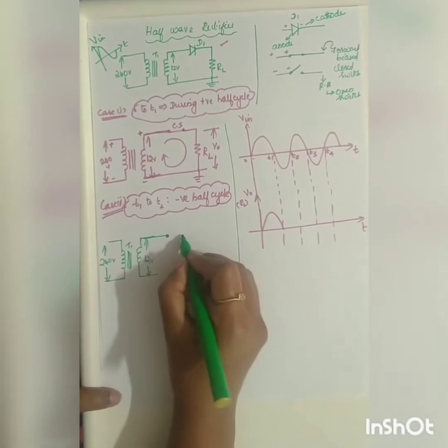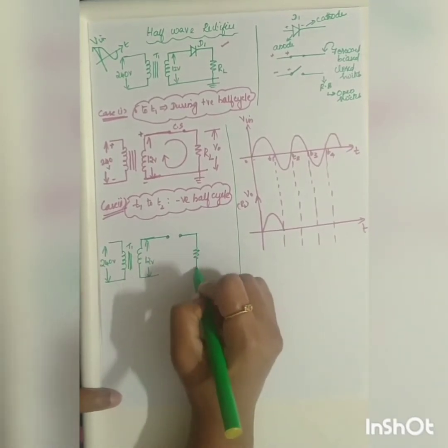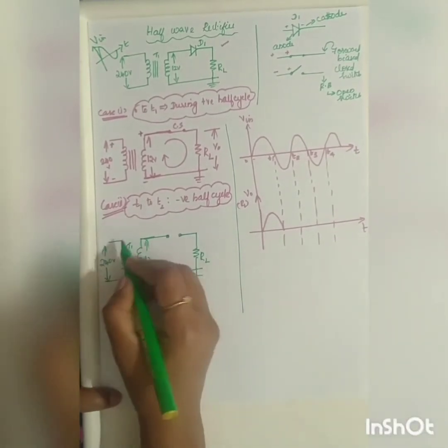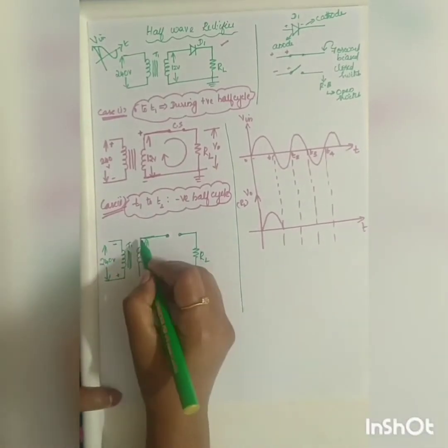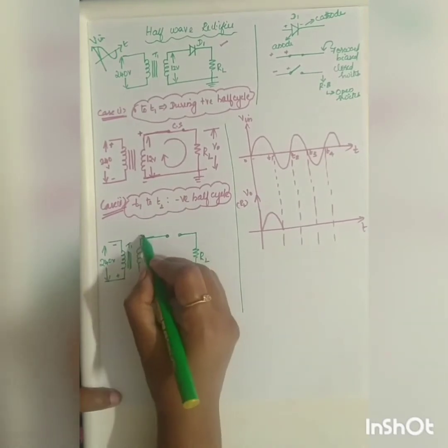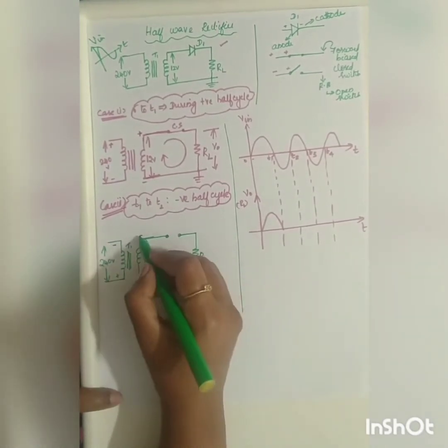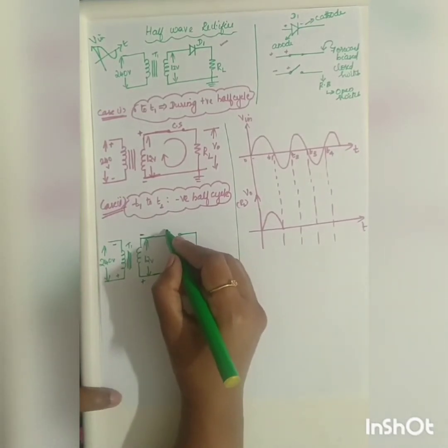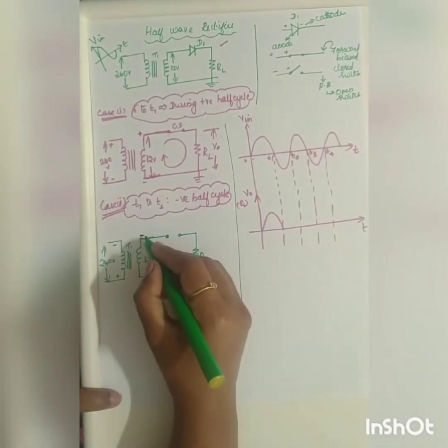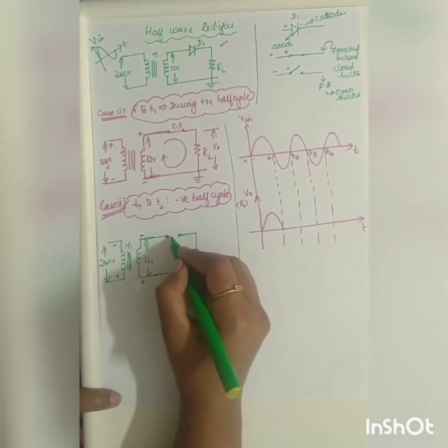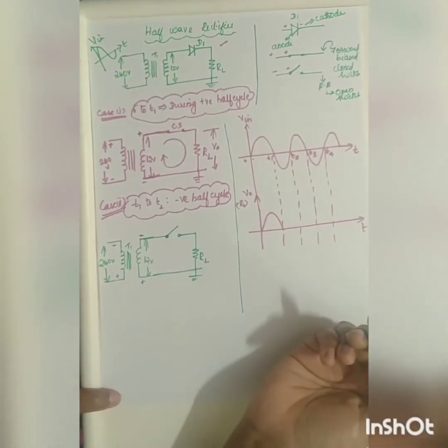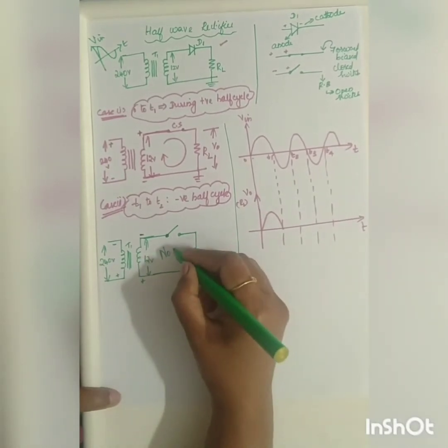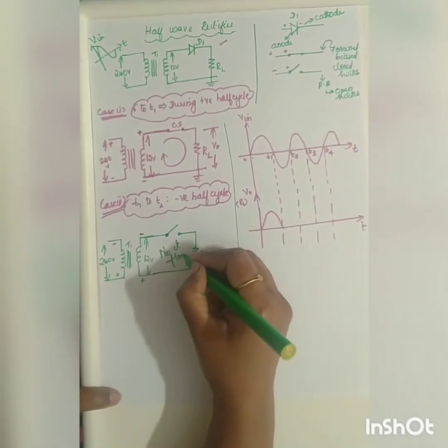Now let me draw an option here. This is going to be your circuit RL. So now what happens here? During the negative voltage, this becomes negative, and this positive. The incoming signal is negative, but your diode here is the anode. So negative and positive, it is reverse biased. So your diode will act as an open switch. There is no current flow, or there is no conduction.